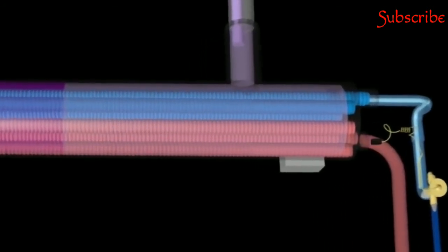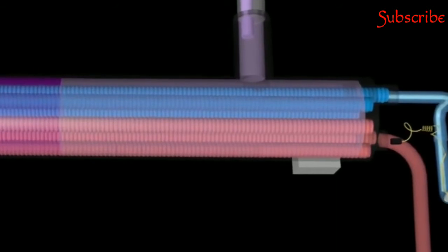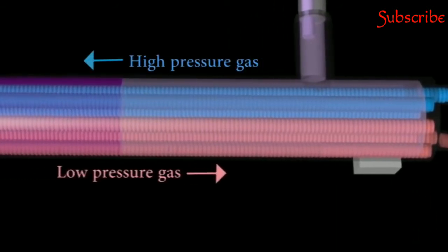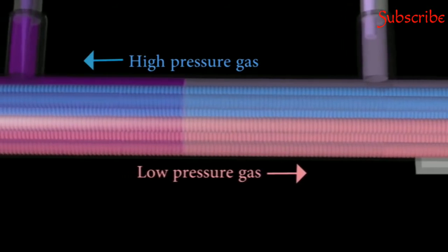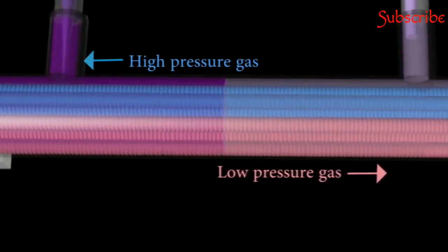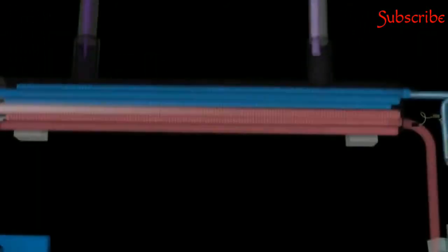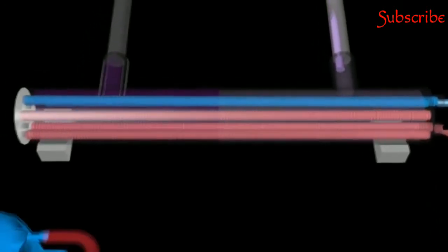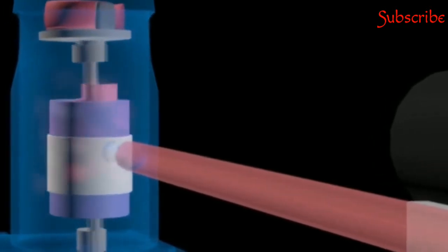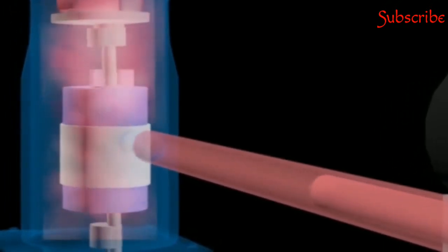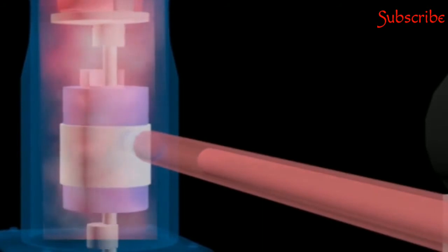low pressure gas. The evaporator most commonly used is shell and tube type, where the refrigerant flows in the tube and the water floods the shell. The evaporator is covered with insulation to reduce heat transfer. The refrigerant in low pressure gas will return to the compressor and continue to the next cycle.